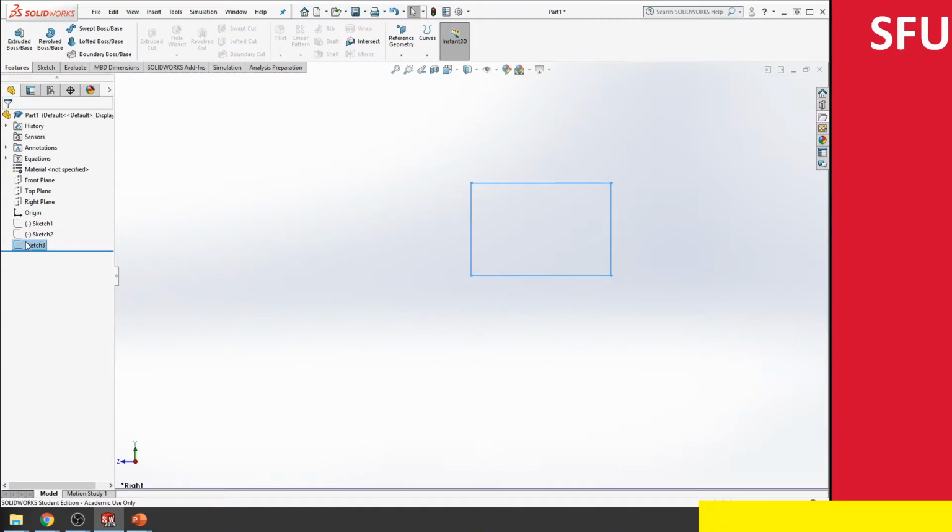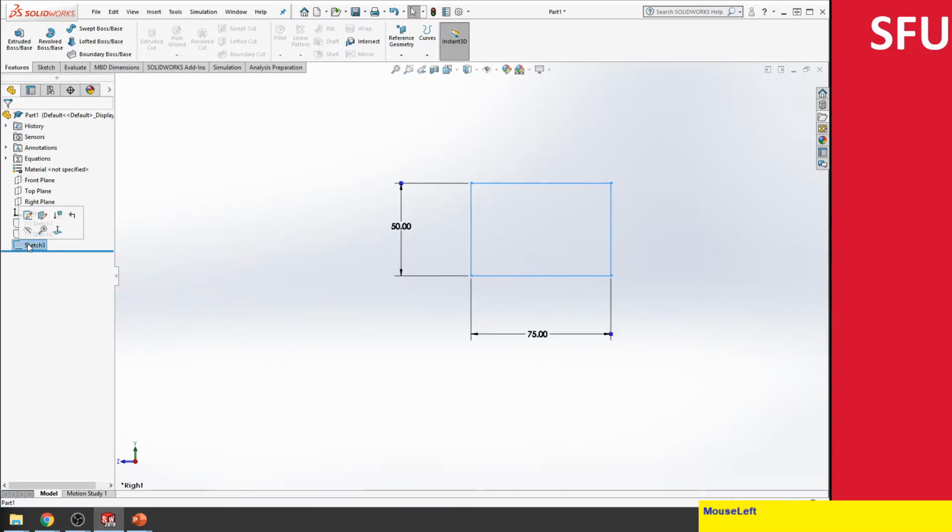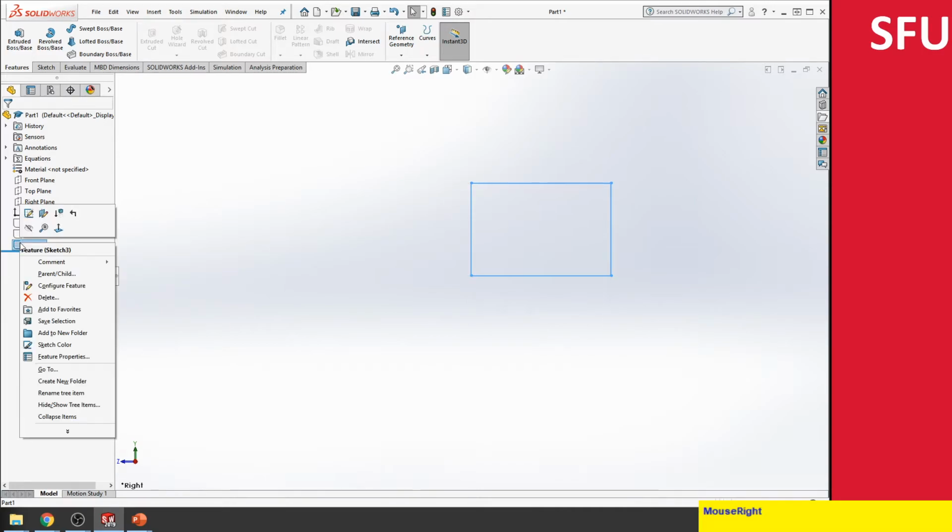So now you have Sketch3. If you wanted, you can rename this sketch to anything you want, and then we can extrude the shape. Notice that if I select the sketch over here, it gives me the option to edit the sketch, and also the option to suppress and do all of the other stuff.